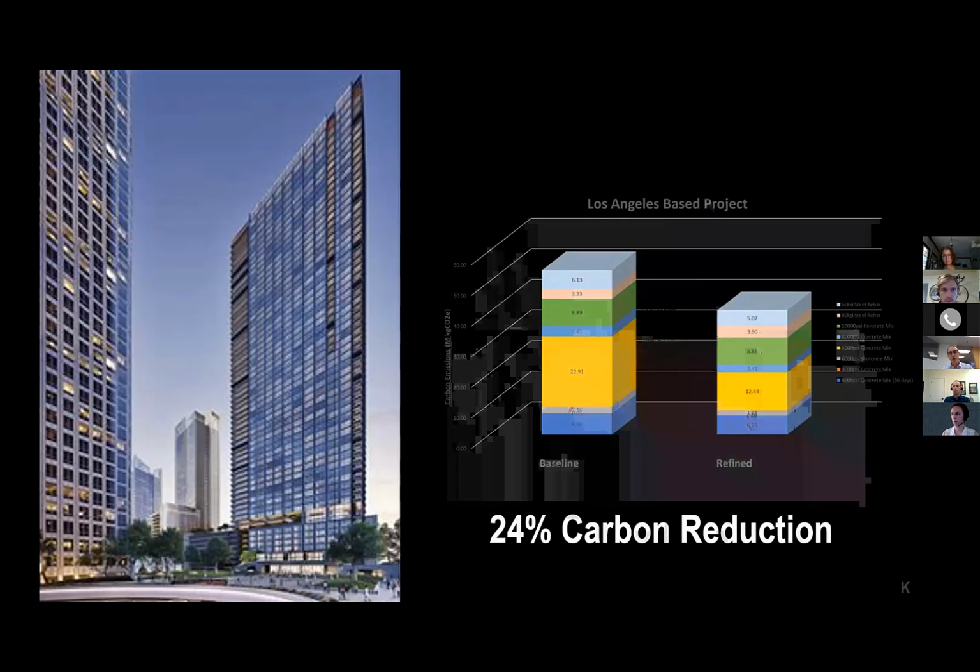On the total project, the single intervention of using the imported aggregates was a 24% carbon footprint reduction across the entire project from what we had as baseline mixes, not against NRMCA, but mixes proposed for this project using local aggregate versus going to the imported aggregates. In fact, it was up to a 47% reduction in cement on the post-tension mix we were looking to use.